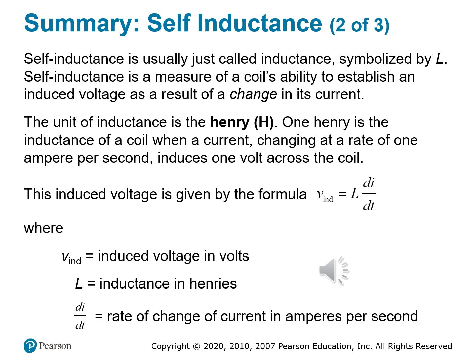If current is steady, no voltage is induced. If current is rising or falling, the coil resists with an induced voltage opposite of the change, thanks to Lenz's law. Well, we can explain it through Lenz's law. It's not that Lenz's law creates this. So if you're working with switching circuits, pulse generators, or high-speed current changes, you'll need to factor in this induced voltage. It can protect, it can oppose, or it can even destroy your components if not properly accounted for.